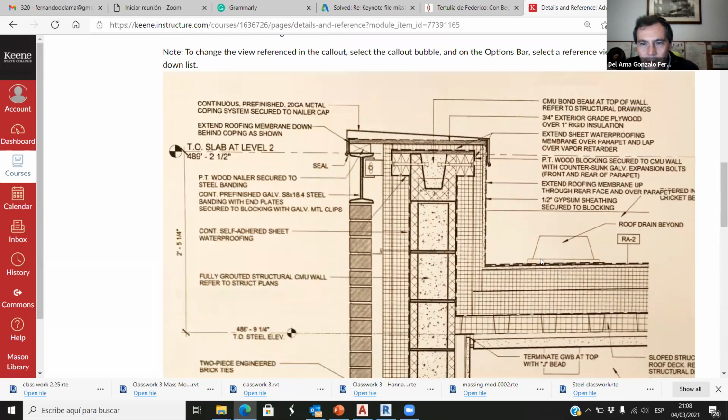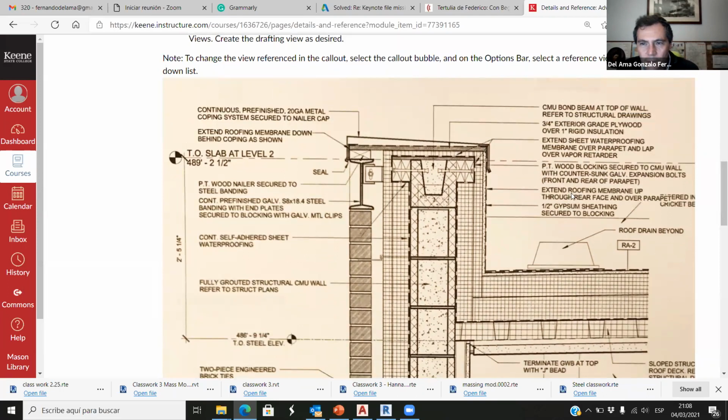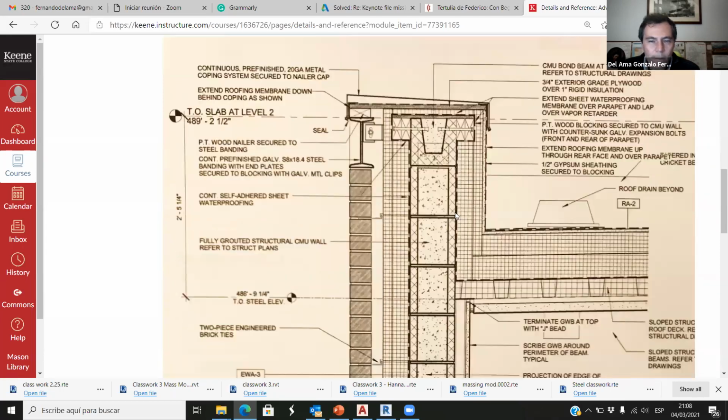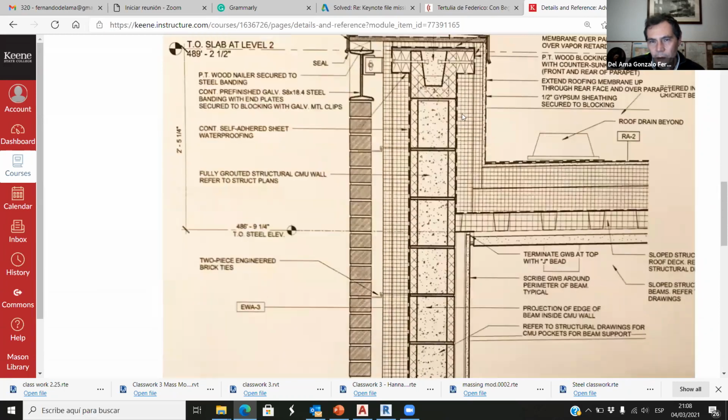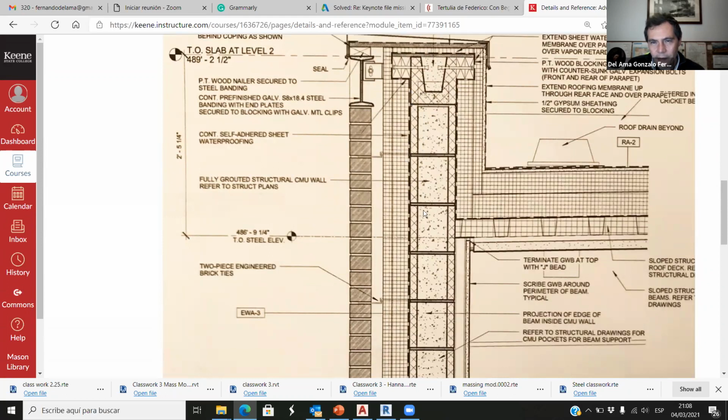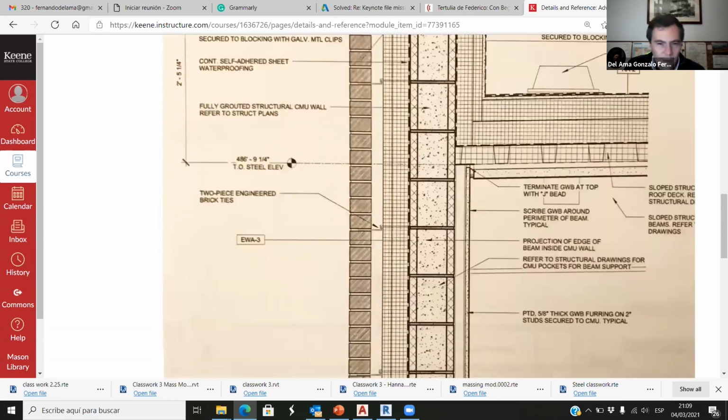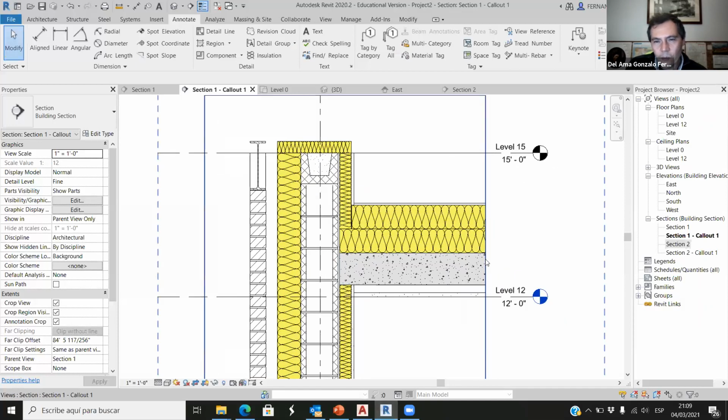I don't know if we can find, this is a roofing membrane. Okay, so this is something, a waterproof layer here, a waterproofing sheet or membrane. Okay, but the idea is that this wrap here inside the thermal insulation should be a vapor retarder, and the other one should be something waterproofing. So let's do that. Okay, so we need 2 different layers, vapor retarder, and then the other one, wrapping this.